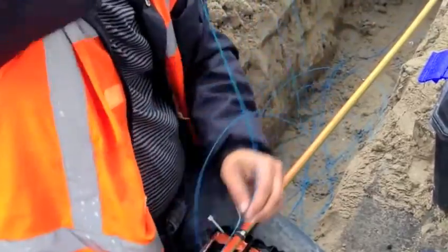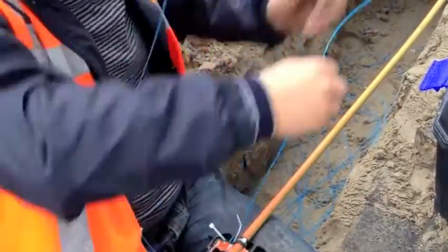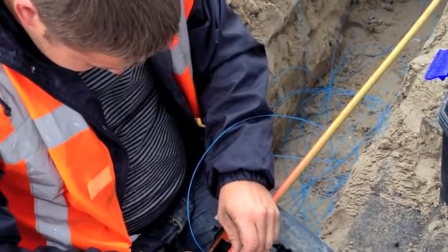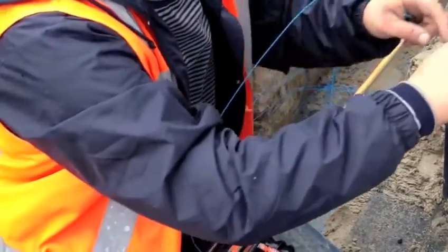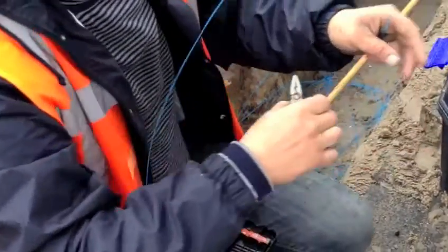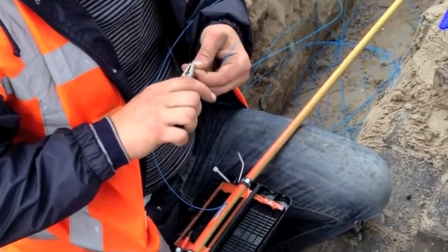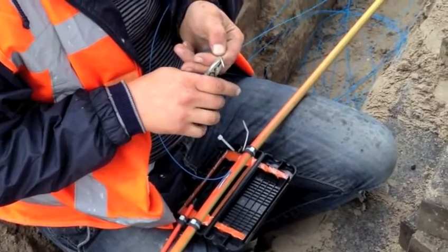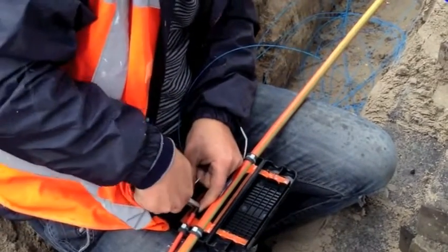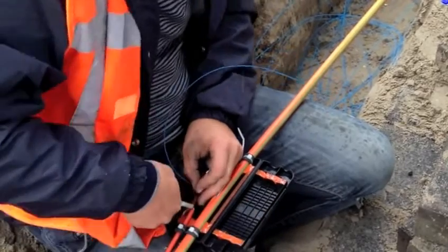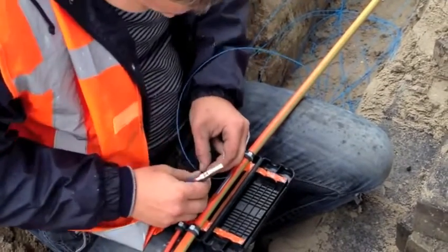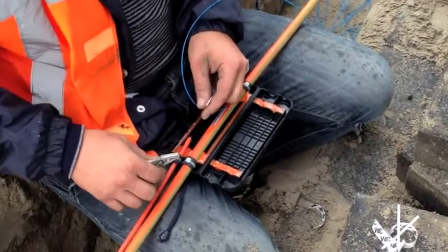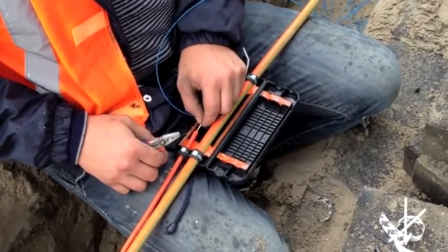These are 2 fibers, but in this specific one, you have 2 fibers and 2 dummies. So on the same side, you can put 4. We can go up to 12, just in case. Then they install a little metal bead on the fiber, just to be connected later to this part. They remove a rubber cap just to avoid water when you pre-install. We go inside. No special splice, just crimp.